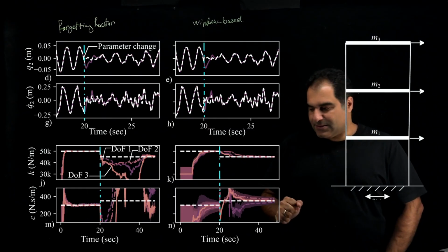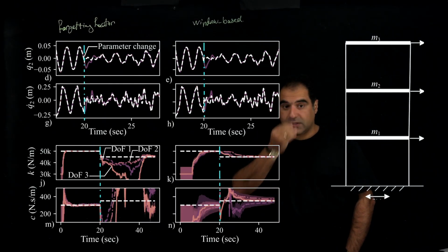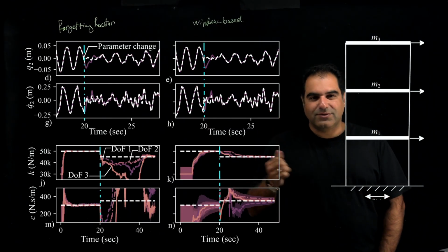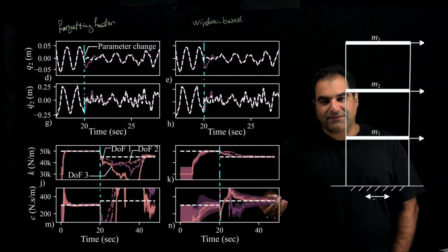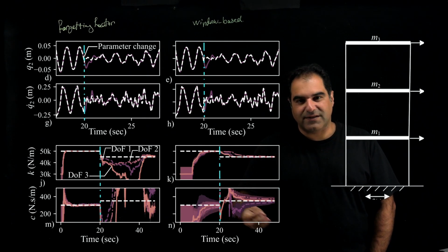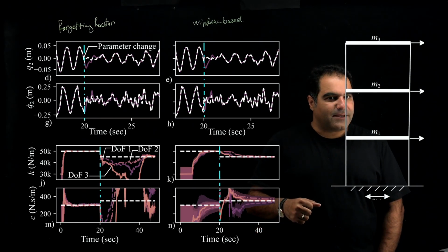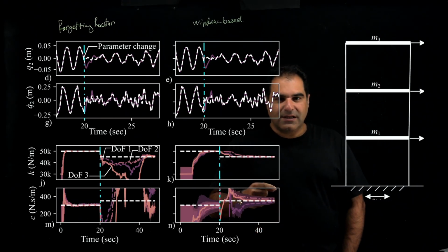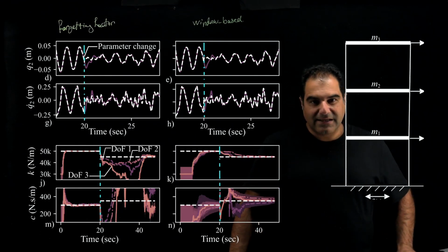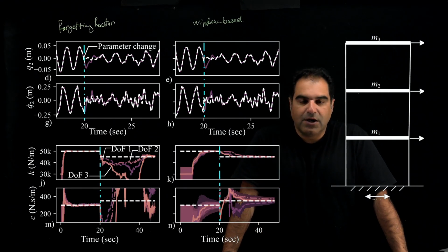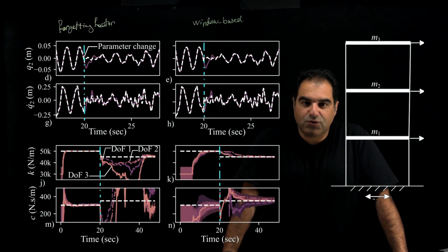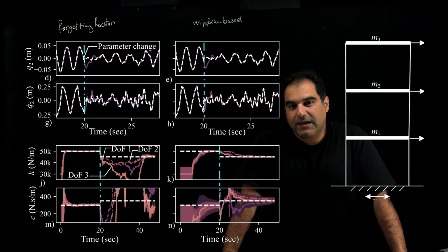Okay, so far in this video, I talked about two different adaptive techniques to be used along with the unscented Kalman filter algorithm to quantify the level of the damage. But for both of these algorithms, we brought some new hyperparameters. For example, for forgetting factor techniques, we have alpha R and alpha Q, which we need to find the optimal value for. And for window-based techniques, we have the window size.